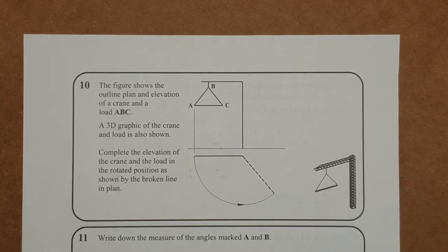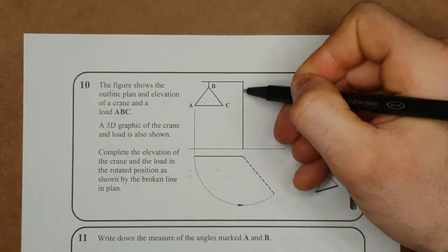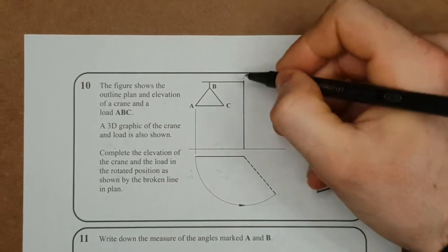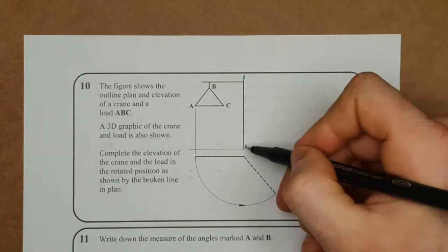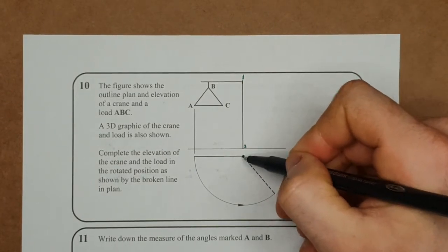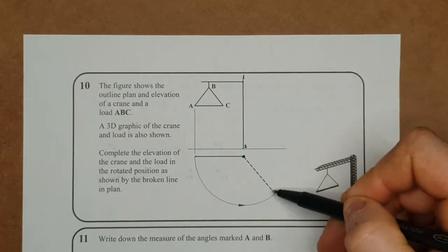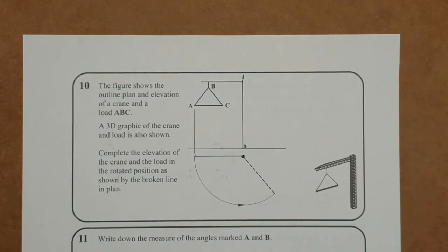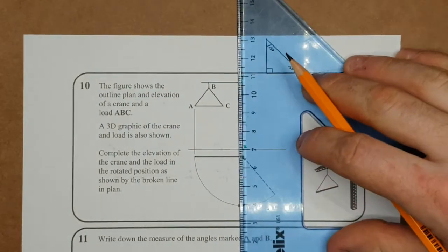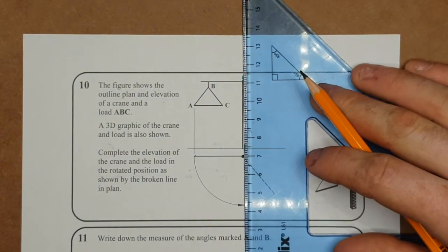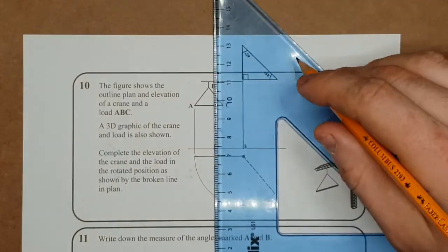First off, where does it pivot? The main pivot of this object goes from point 1 to point 2. That is the hinge. The hinge appears as a point view right here in plan. I have my original position and I have my rotated position. The first key rule when it comes to rotations is that once you have your labelling done, we bring all parts of the object and project them onto the original position first.